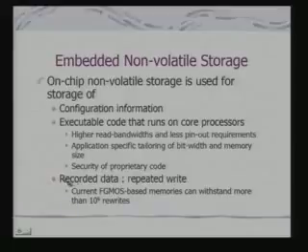The other interesting thing which is important is security of proprietary code. Since it is sitting inside the chip, it becomes difficult to access and know what the code is all about, and then do some kind of basically forgery in the sense of taking the code and using it for other purposes. Other thing is that recorded data, typically your voice recorders, your cameras, they all use flash, which actually enable repeated write. Currently these FGMOS based memories can withstand more than 10 to the power 6 rewrites, and another observation is that once charged, the charge leakage time can be as large as 10 years. So, that is why many of these recorded data, when you have a speech recorder or a camera, you actually have these flash cards to store the data, or the flash memory to store the recorded data.